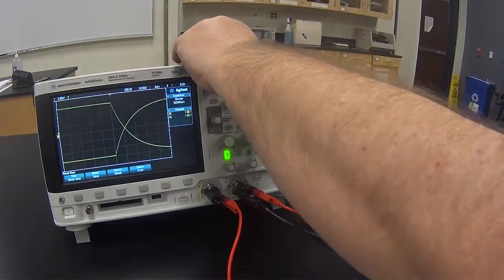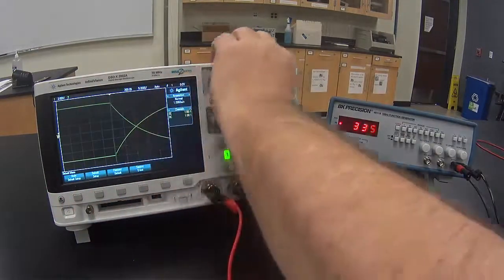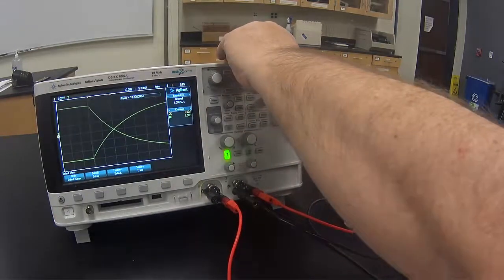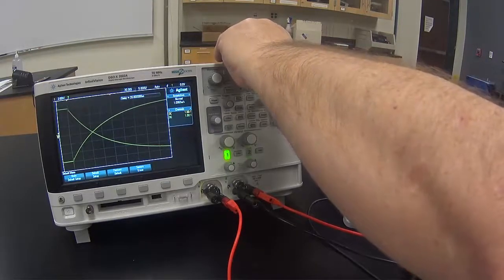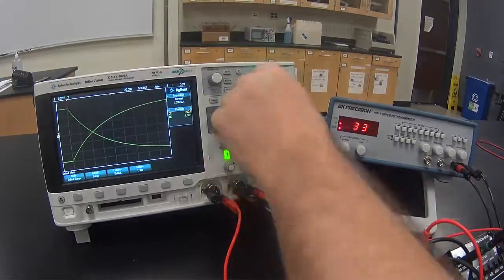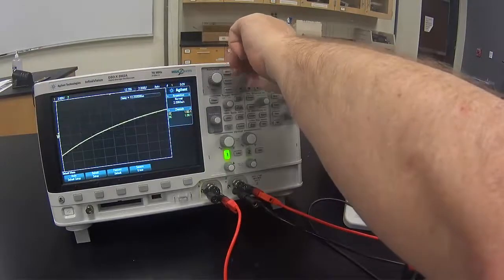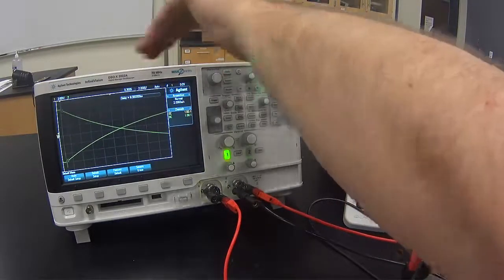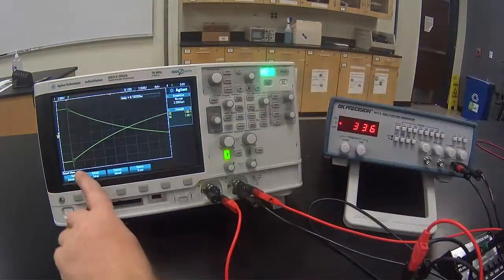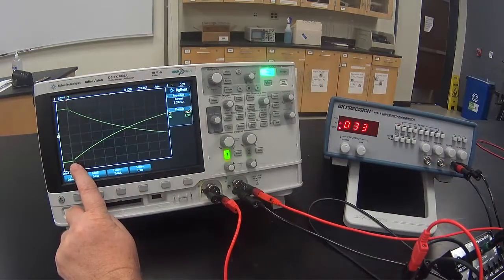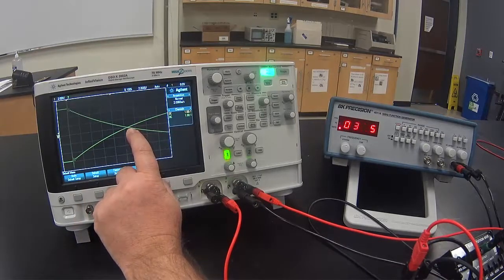My goal at this point is to stretch out the time signal as much as possible while still being able to show the curve go from the baseline to 3 divisions up from there. You may have to do a horizontal adjustment to keep the baseline still visible. This is stretched out pretty far. I have several time divisions for it to go up 3 voltage divisions.